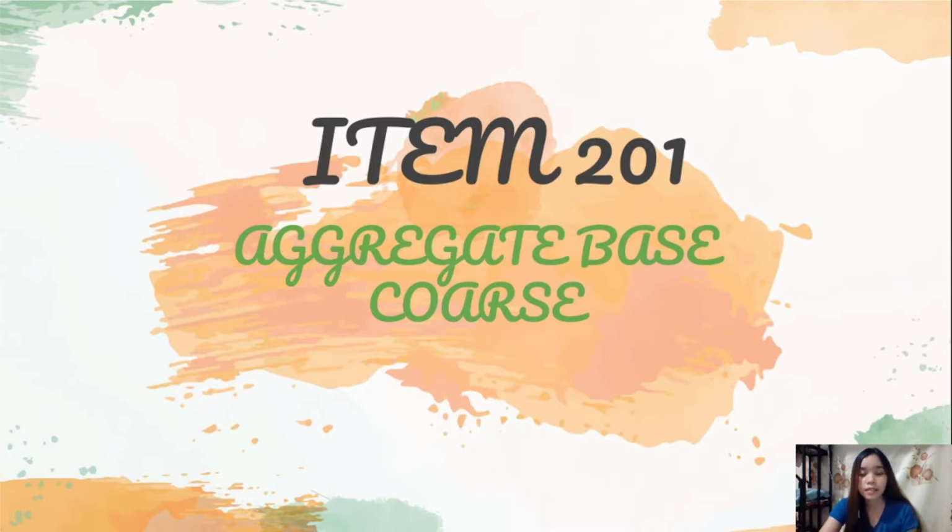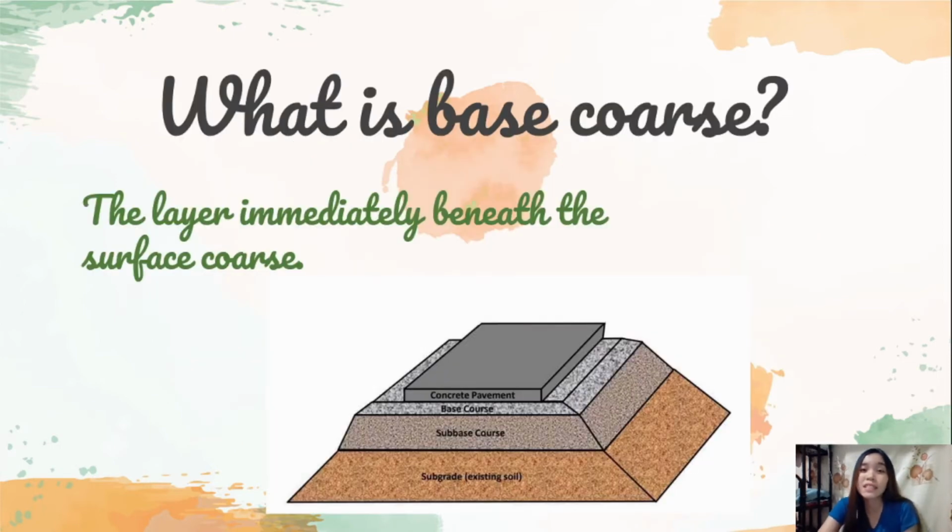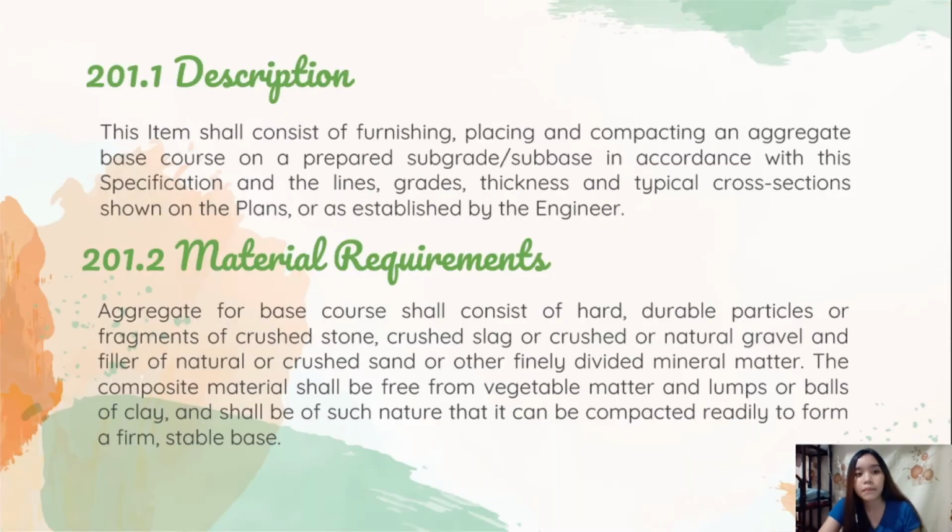Next is item 201, which is about the aggregate base course. So what is base course? It is the layer immediately beneath the surface course. The base course provides additional load distribution and also contributes to drainage. Base course is usually constructed out of crushed aggregates.